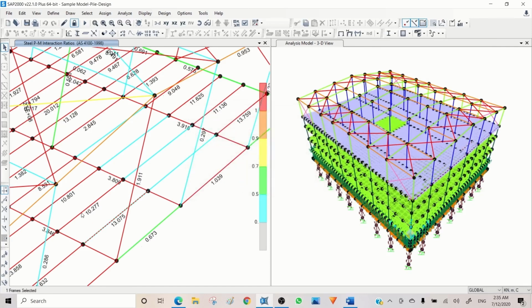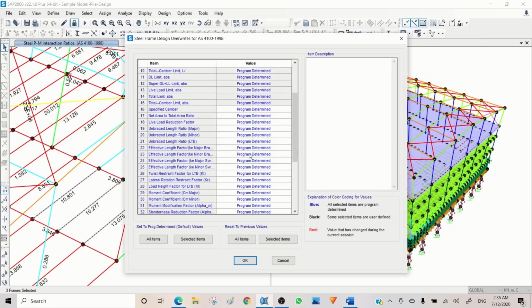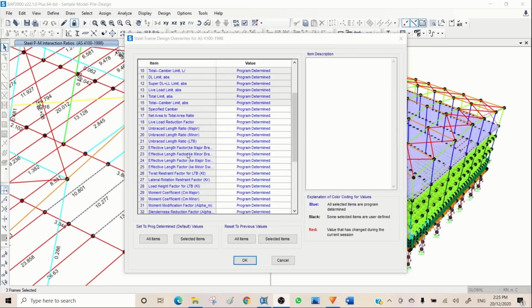But even if you choose them and decrease the lateral stiffness here, and this time I intentionally just changed the lateral bracing length ratio to show you the other factors like unbraced length ratio for buckling are not effective in increasing the bending capacity.